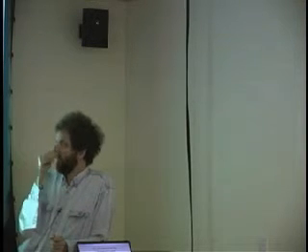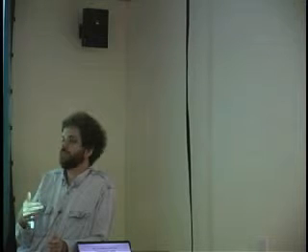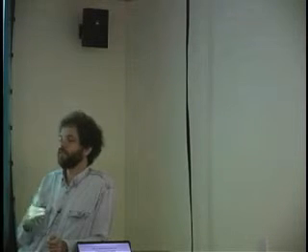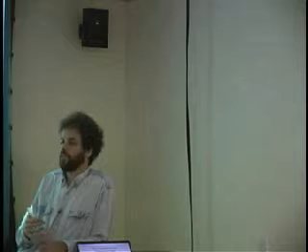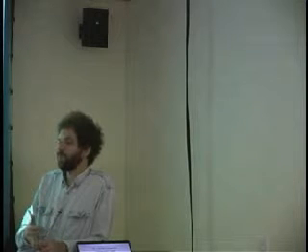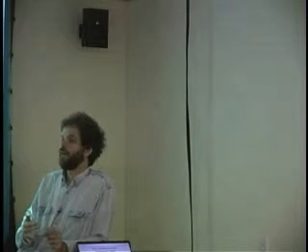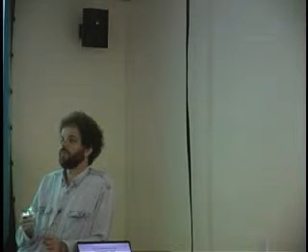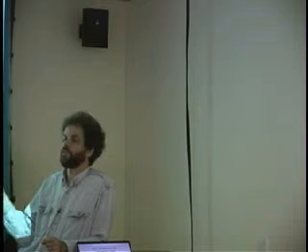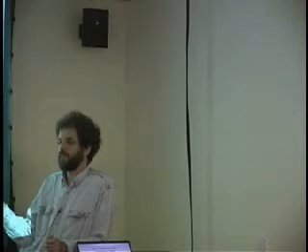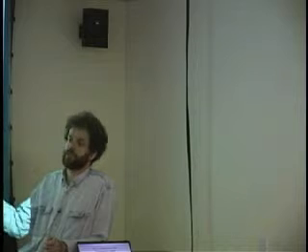So I guess the lesson I want you to take away from this is we're being terribly restrictive here. Single input change, only trying to remember a 0 or a 1, and hazard-free circuit. Okay? And under those conditions, we're able to generate a circuit like this and be assured that it's going to work. But in general, circuits like this don't just work.